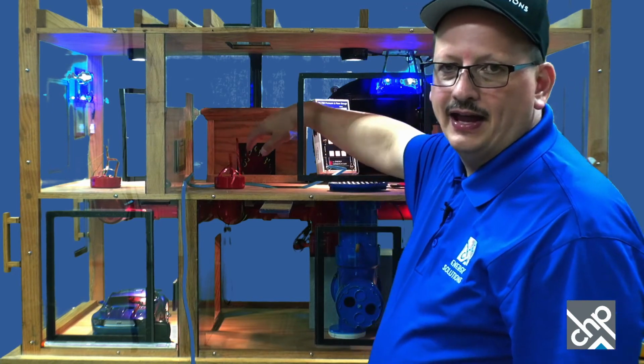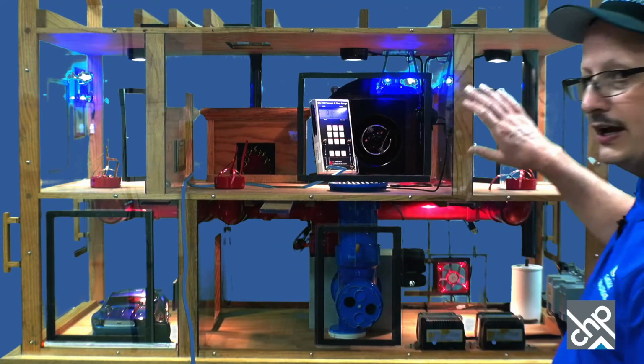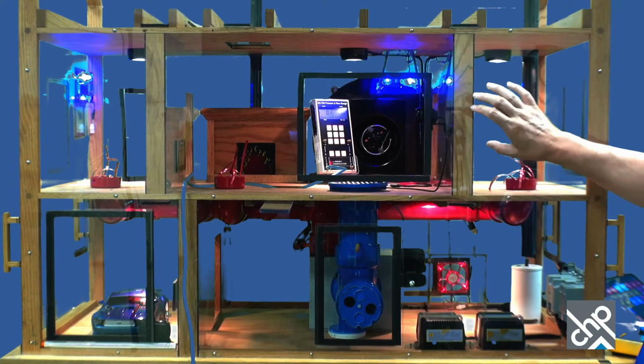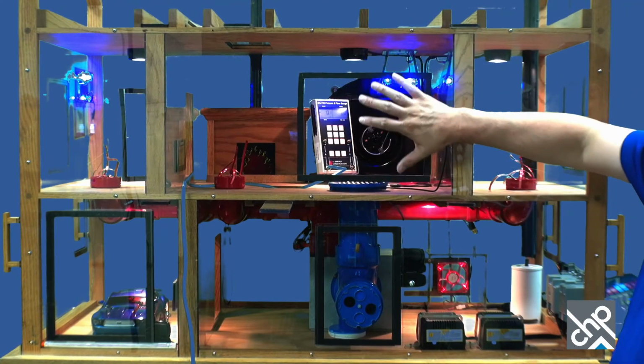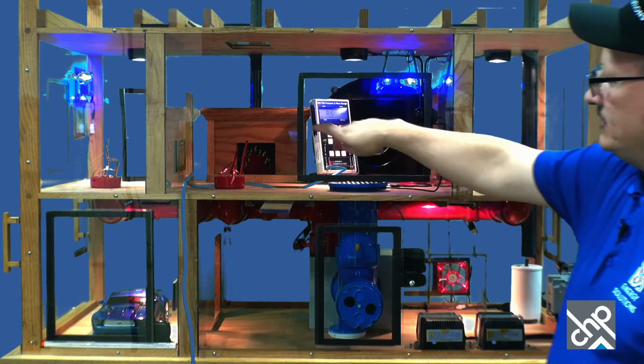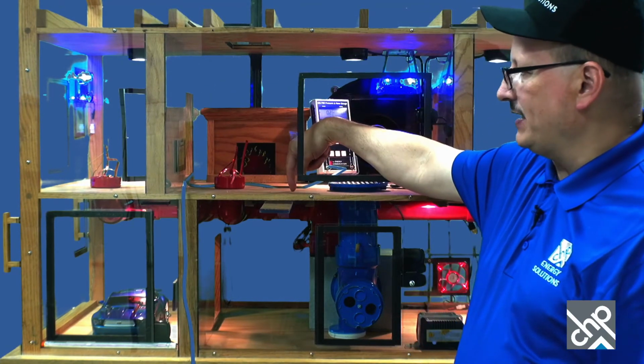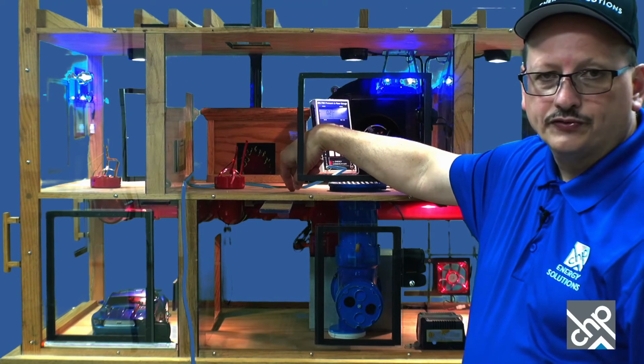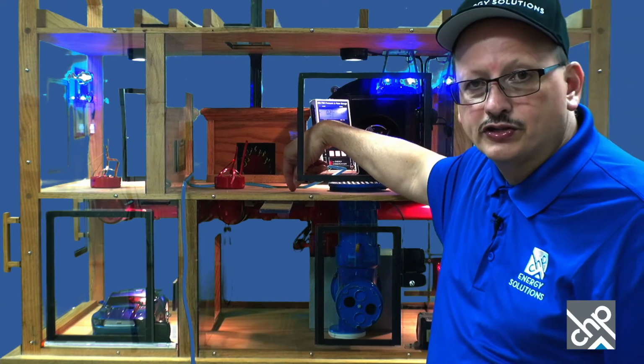Now the bedroom, at this point, all we have on is the exhaust fan. So you don't need to check the bedroom doors, because if there's no exhaust fan behind it, you just want to keep that door closed. Like I say, the bedroom door over here, I'll close it now where you can see it. There's no fan behind it. So when you close this door, it reduces the volume of the CAZ. Whereas the door to the basement has a fan behind it. We want to know, is it better or worse with the door open or closed? And we want to put it in whatever the worst position is.